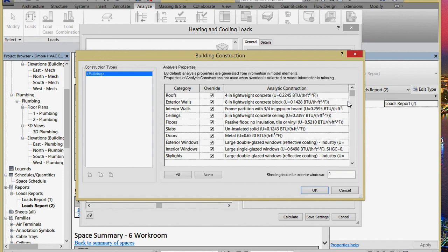Okay? If we were up in Lake Tahoe or a very cold weather climate, we'd have to put at least an R38. What I'm doing is thinking about prescriptive standards that are part of California's Title 24 Energy Code. They're the easy way of getting some general guidelines. You could always go through an engineer, something that has higher or lower values, and be very precise about the amount of heat that's flowing in and out of that surface. But for the real simple answer, they'd say, oh, you're putting a roof in Palo Alto? It should be R30. Okay, if it was a colder weather climate, it might want to be R38.